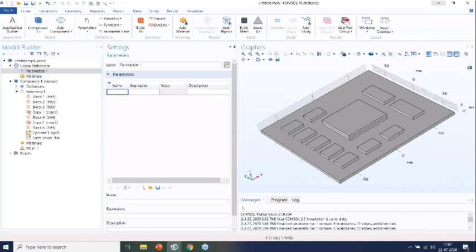Let's say I'm first defining one parameter as air spacing, that is air underscore sp. You can give any name of your choice, but just remember what name you are providing. And for that I'm going to provide the declaration value as 3 mm.